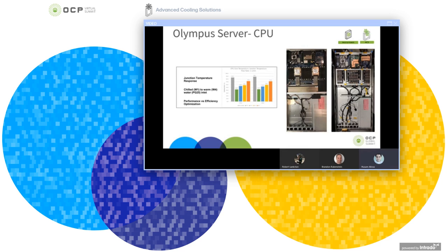One thing to point out, though, in this slide is that, as you can see, there are cold plate or liquid-cooled modules on almost most of the components: CPUs, DIMMs, M.2s, and FPGAs. And this affects the heat pickup ratio between the air and the liquid. But in reality, that decision has also to be TCO driven, taking into account the power reduction because the fans are ramping down further. However, we need to take into account the effect of the added cost for the extra modules.